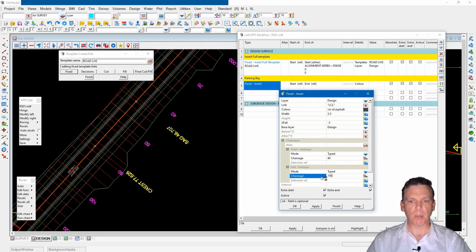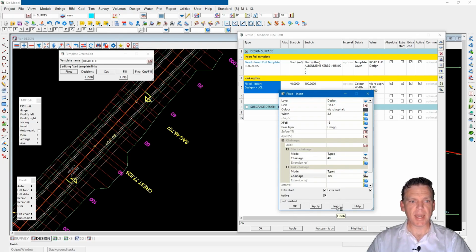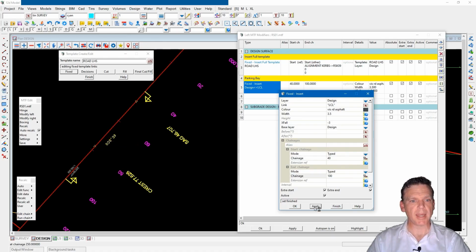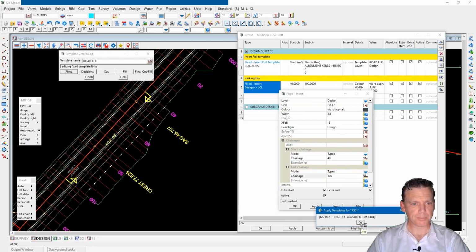Now you'll notice when I hit apply here, it saves the answer and it's put the yellow arrows on my plan view there, but nothing's actually been updated. I actually need to come all the way across to here to hit the word recalculate. Or a quick little tip, if you actually click on auto recalculate, any of the apply buttons at any level here, as soon as you hit them, it actually will go through and calculate and apply it for you. And you can see there, it's applied that quite nicely for me and introduced my new link.